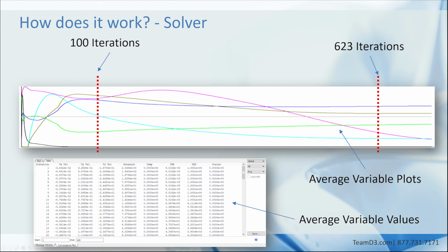It can take hundreds or thousands of iterations to arrive at a converged result. Depending on the size and detail of the model and the physics being simulated, this may be done for multiple variables at millions of points in the domain. This is why CFD is pretty much impossible to do by hand, and even still a challenge for modern computers. Analyses can take under an hour, but it's not uncommon for solve times to take multiple hours. Solve times that take days are not as common. Typically, there are multiple options when it comes to solving. You may be able to send the analysis task to another dedicated workstation or cloud resources on off-site data centers. Autodesk CFD includes both of these options.